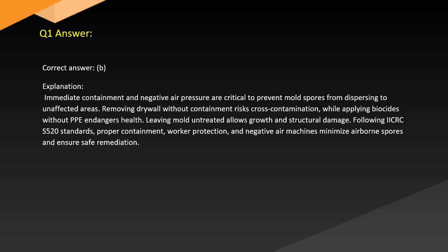Answer. Correct answer: B. Explanation. Immediate containment and negative air pressure are critical to prevent mold spores from dispersing to unaffected areas. Removing drywall without containment risks cross-contamination, while applying biocides without PPE endangers health. Leaving mold untreated allows growth and structural damage.